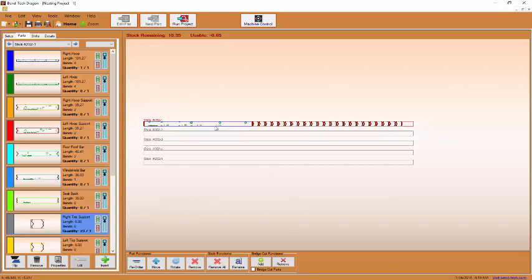Now, with this stick, say we were to cut this stick out and we truly wanted all these 6-inch parts, I would highly suggest taking this long part and placing it at the end of the stick, simply because the Dragon machine has a 14-inch to 16-inch dead zone, and that's why you're seeing here it's not filling up the entire stick.